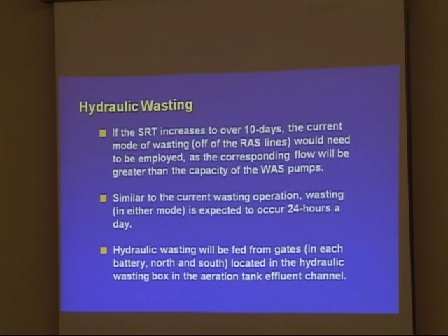And so if you're going to increase the SRT over 10 days, the current mode of wasting, which you used to use back in the day, off the RAS lines, would have to be employed. And that corresponding flow would be greater than the capacity of the WAS pump. So then you're going to end up wasting off of the RAS line, a more concentrated amount of